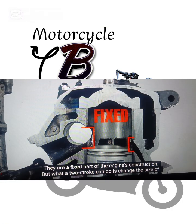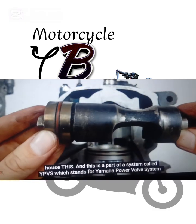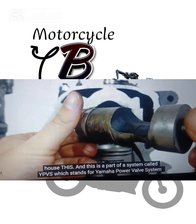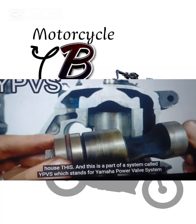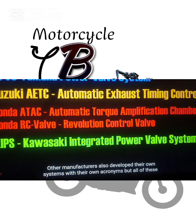They are a fixed part of the engine's construction. But what a two-stroke can do is change the size of the exhaust port. And this finally brings us to the big round hole in the exhaust port. It's meant to house this. And this is a part of a system called YPVS, which stands for Yamaha Power Valve System. Other manufacturers also develop their own systems with their own acronyms, but all of these systems have the same goal.